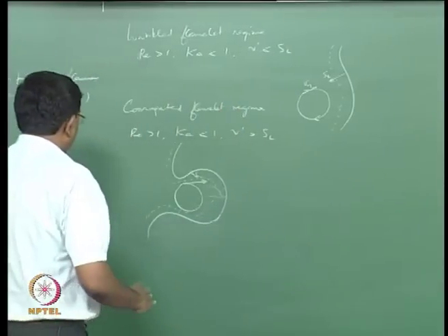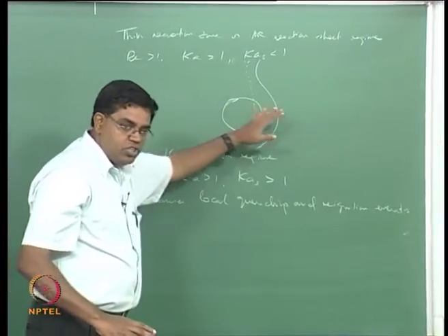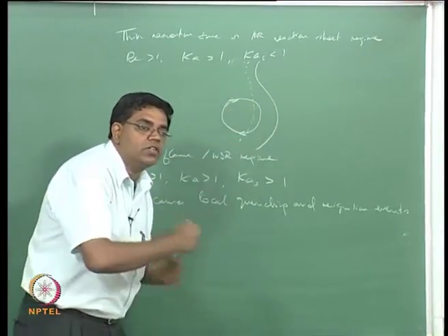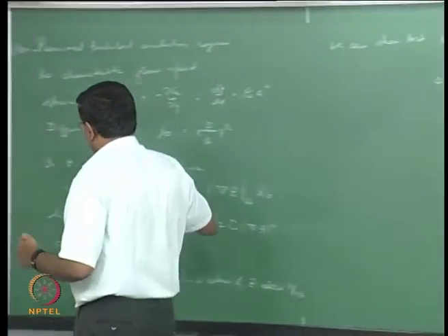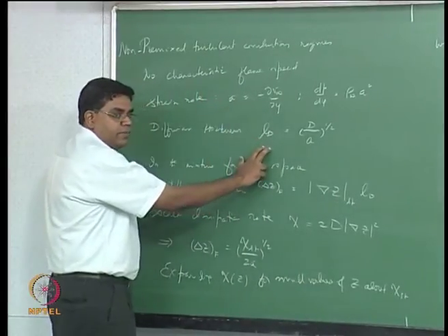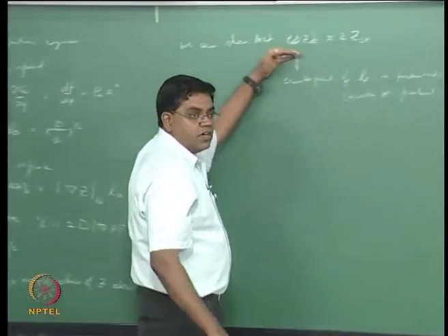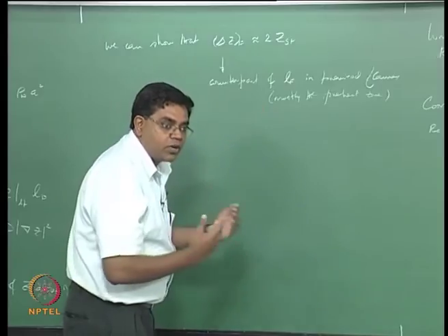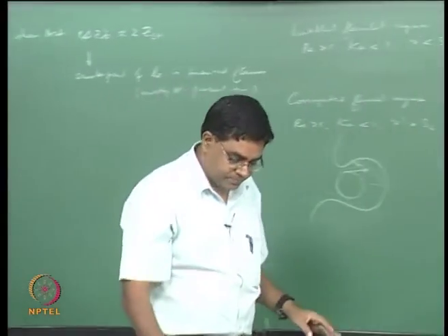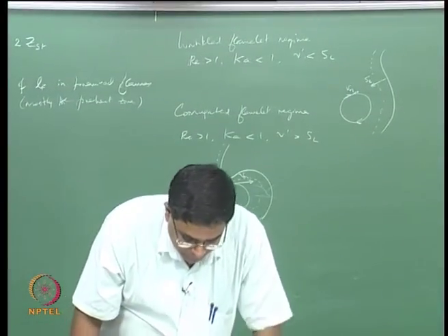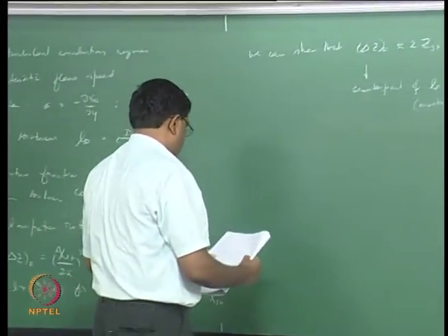So effectively, up to here we have been mainly interested in the premix flame regime diagram, what the preheat zone is doing relative to the eddies. Similarly, if you are now thinking about a corresponding diffusion thickness for the flame, we should be worried about this in the mixture fraction space, how that is going to interact with the eddies, and that is the counterpart of mostly the preheat zone of the premixed flame. And here again the laminar ideas are coming back to help us.